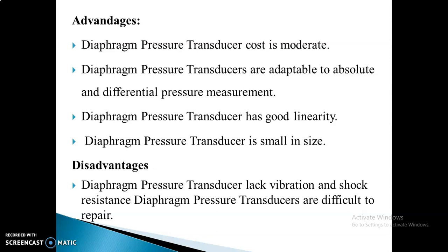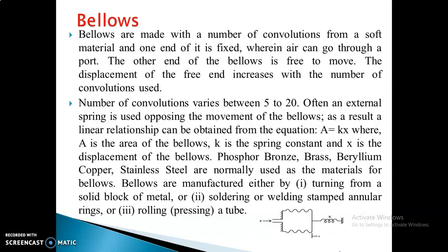So what are the advantages and disadvantages? Advantages: cost is moderate, adaptable for differential pressure measurement, good linearity. Disadvantage: it lacks resistance to vibration and shock. Once it is damaged, it is not easy to repair. The third one is about the bellows.